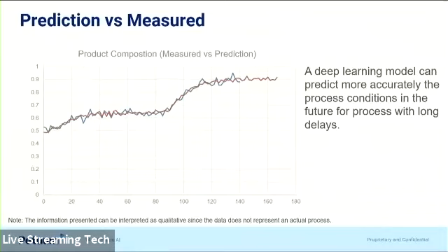So something that I think is very important is the capability of the system to predict the process in a long term. There are systems in the oil and gas, where we have, let's say, a fractionation system, that might have more than 2 hours residence time. So you take an action, and then you are going to see the result 2 or 3, 4 hours later. So we need to have the correct deep neural network that will capture that dynamic for those processes. So we need to be sure that we can create this.